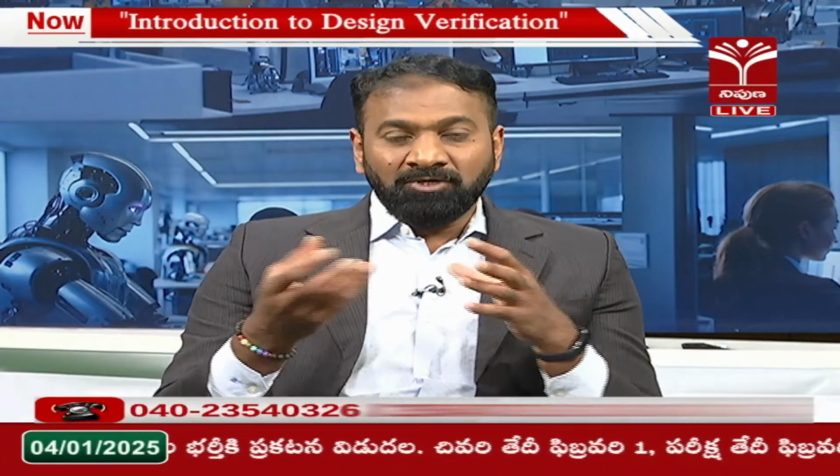Now if you don't have formal verification, you have to spend a lot of test bench development time. While the test bench is being developed, you can still capture a lot of bugs by using formal verification, if you have a netlist available, or you can apply formal verification on the RTL design itself. So formal verification is gaining a lot of traction in the industry now, and it uses mathematical modeling to prove these two designs are equivalent or not, or to ensure the functional correctness of the design is met or not.